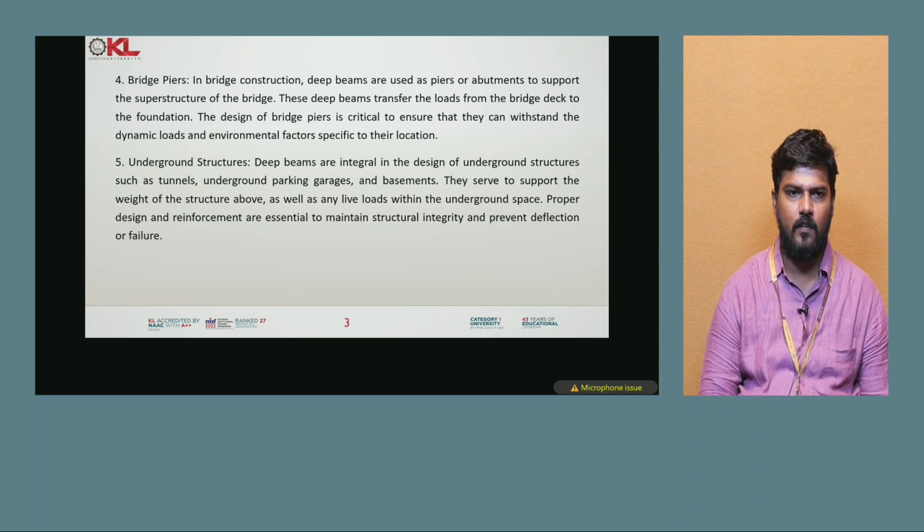So coming to the next one, the bridge piers. In bridge construction, deep beams are used as piers or abutments to support the superstructure of the bridge. These deep beams transfer the loads from the bridge deck to the foundation. The design of the bridge piers is critical to ensure that they can withstand the dynamic loads and environmental factors specific to their location.